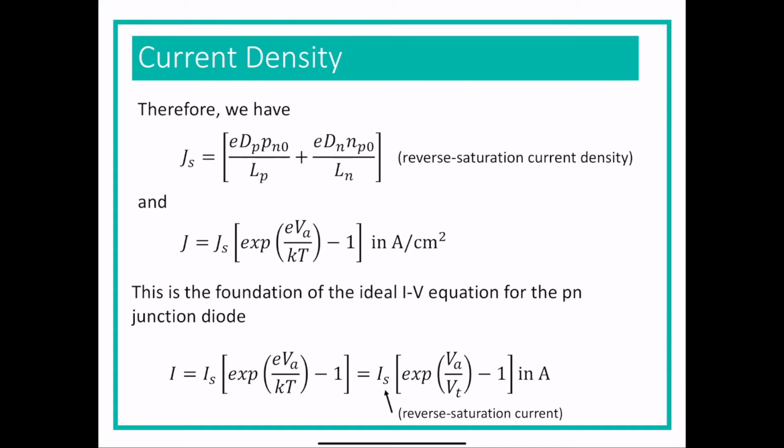And this is the diode current equation that we get when we do pretty much any kind of measuring and creating of diode curves. And the saturation current can be listed in a data sheet, the reverse saturation current, so it's relatively easy to find.